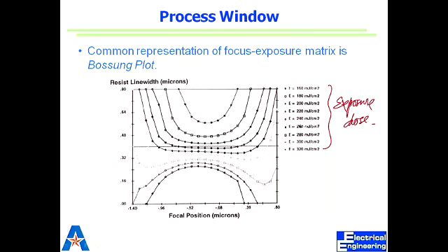For your focus, you have to see depth of focus on both sides of the plane, plus and minus. But the line width is decreasing with increasing distance. So this is probably the region where your exposure will work, right? Because away from that plane, you will lose. Now, you have to think in 3 dimensions. I have this plane where I'm impinging my line, and it has to deliver energy. There is some thickness, which is in minus, this is in plus. Only within a certain distance will I get my energy transferred. At that point, I can make a certain width of line. I cannot make it bigger or smaller than that.